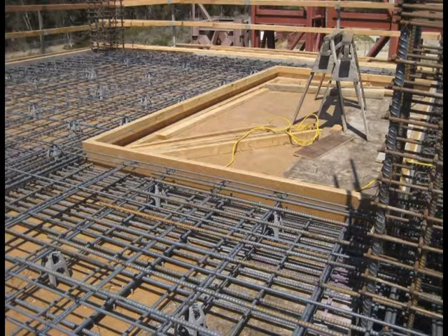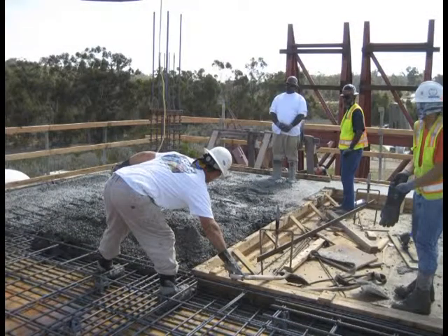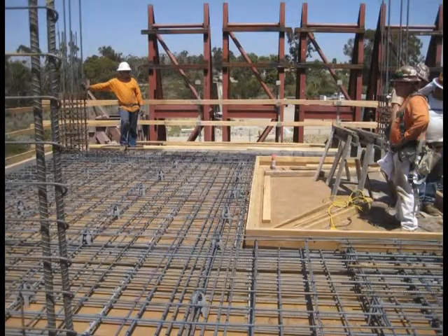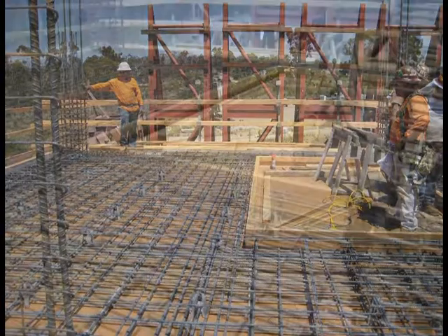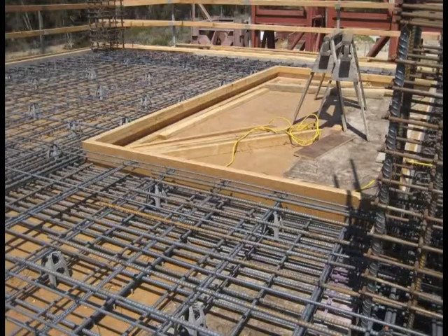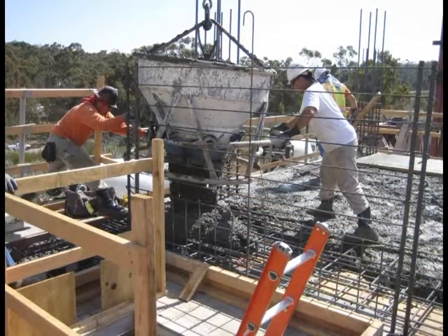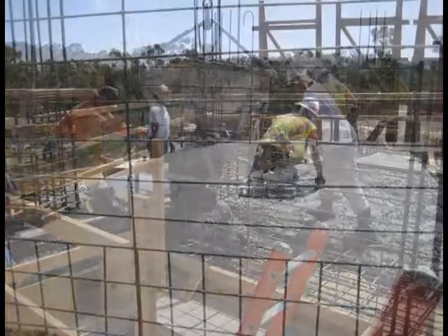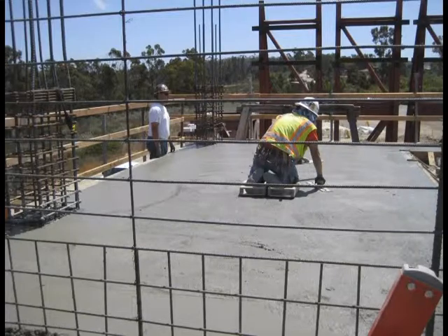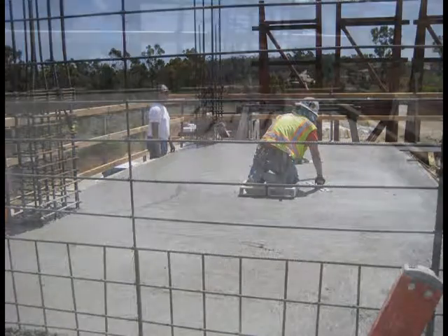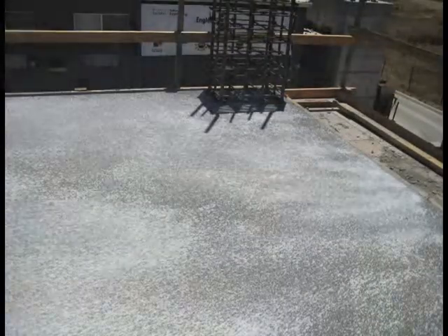In this 5-story building test, openings in the floor slab reinforcement were provided in order for the staircase and elevator to be installed, as well as service pipes. Reinforcement around these penetrations through the floor slabs was more concentrated due to the fact that there would be higher stresses surrounding the openings. After placing reinforcement, the concrete was poured and the surface of the floor slabs was screeded to level and smooth them, just as was done with the shear wall and columns on the ground floor.